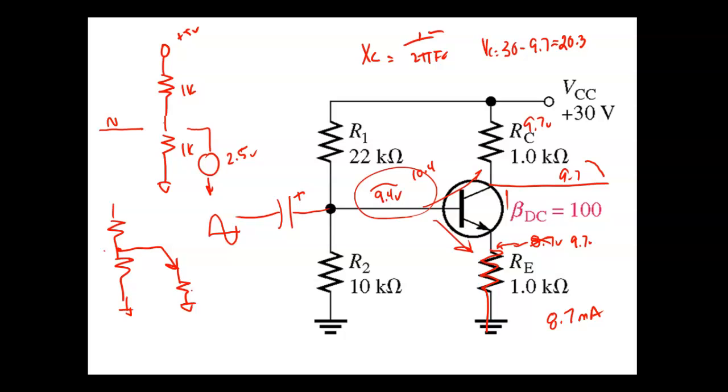So what would be the purpose of me having an amplifier that does not give me a gain more than 1, right? And we'll see how we can calculate the gain. Basically, the gain is this guy divided by that guy. So 1K divided by 1K, that's 1. But if RC was 2K and RE was 1K, then the thing would have a voltage gain of 2, which means I would get twice as many volts out.